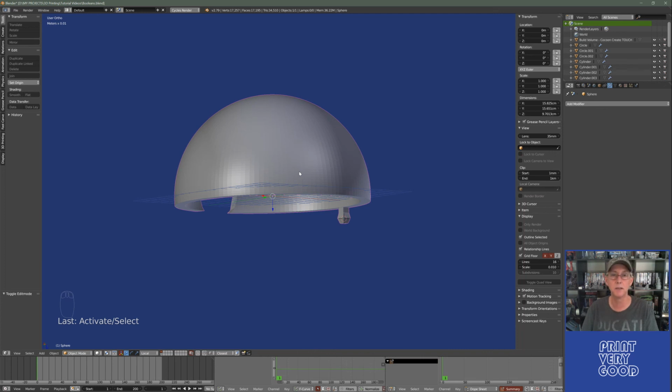Carve never lets me down. B-mesh can be flaky, as you saw. Most of the time it works, but sometimes it doesn't. So I always use carve. And once you've run a Boolean operation, make sure you remove any doubles. Before you do anything else, remove doubles, and then you can do another Boolean operation, and just keep going. As long as you remove your doubles as you go, you'll be fine. So I think that's it for now.